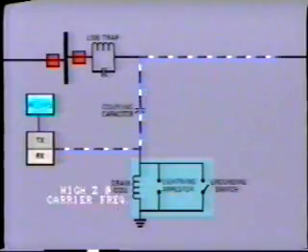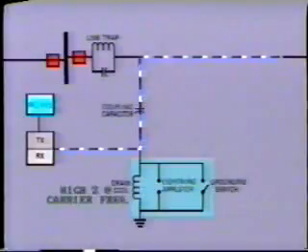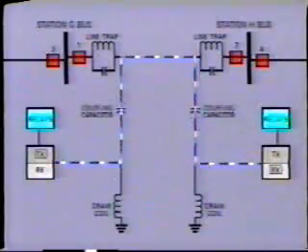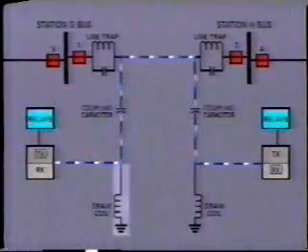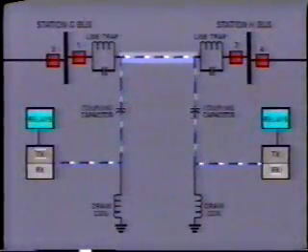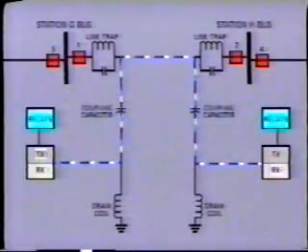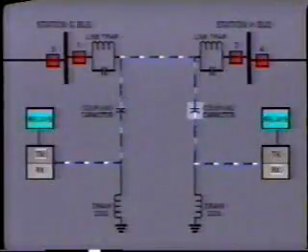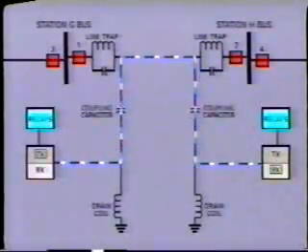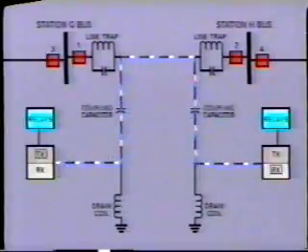This signal will pass easily through the capacitor to the transmission line, but it will be isolated from ground by the high impedance at carrier frequency of the drain coil. In essence, the transmitter voltage signal is applied across the coil between the line and ground. The signal current circulates through the power conductor, out to be captured by the receiver through the coupling capacitor at the far end. This is where only one power line conductor and ground is used to conduct the carrier signal.